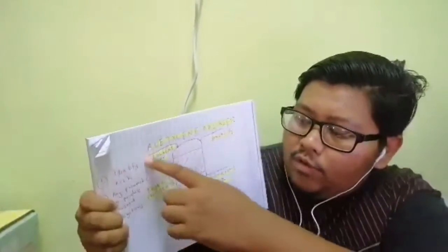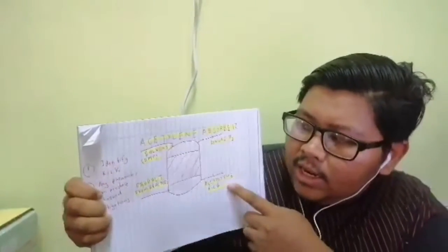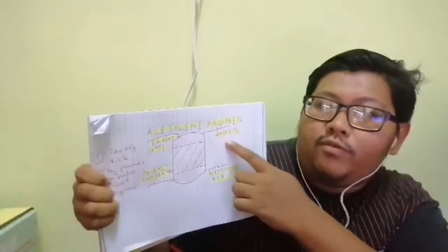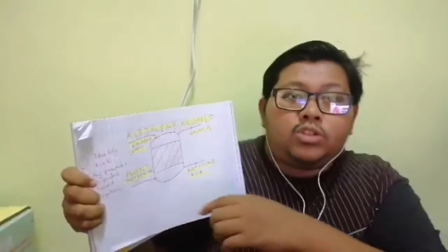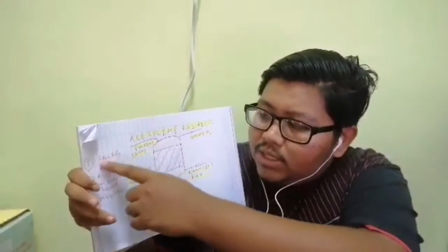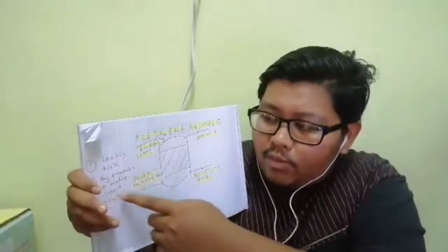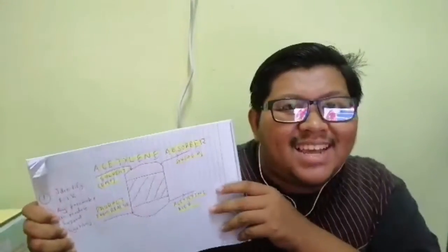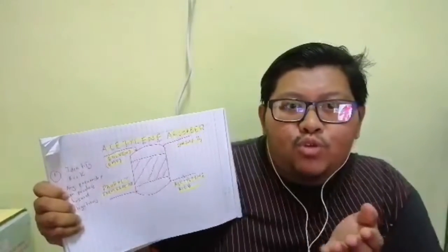The solvent absorbs the acetylene, and the syngas, which consists mainly of hydrogen, will separate at the top. As you can see, there are many potential risks here as we deal with H2, acetylene, CO and CO2, which are highly flammable. So in this video, we will discuss the risk. We will point out any parameter that can produce a hazard, and we will suggest a mitigation for this plant. Now we will continue to my friend.